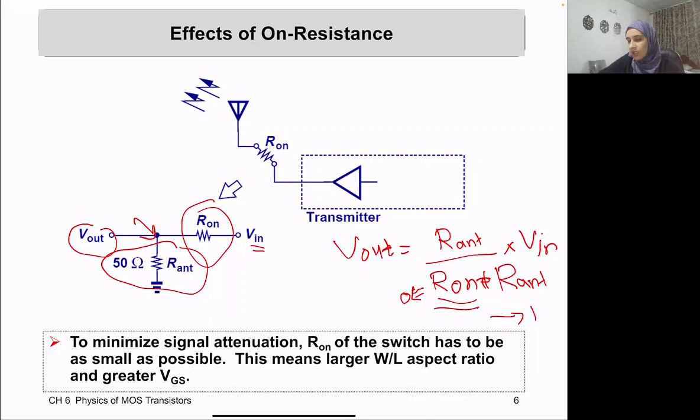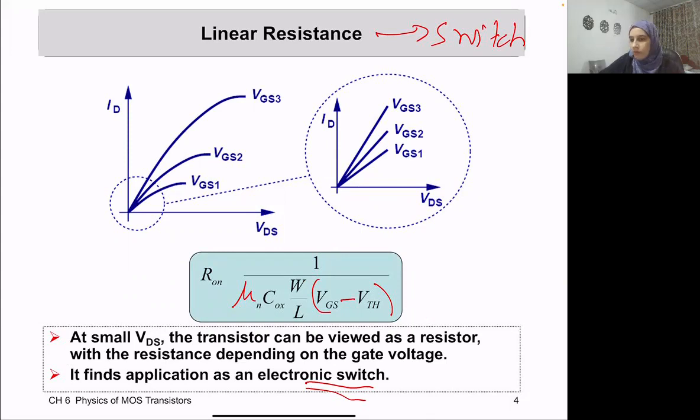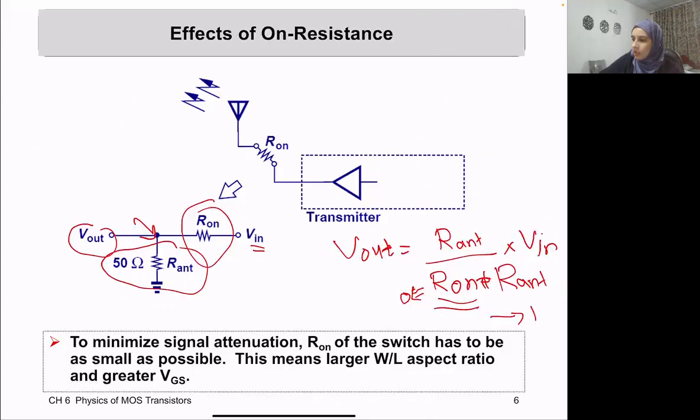Normally, there is even a little impedance, but it's there. And in order to reduce this impedance, as you remember from the relation that we discussed here, either I make VGS minus V threshold large, or I increase the W value. So normally we have a larger width transistor in order to act as a switch with a small on resistance.